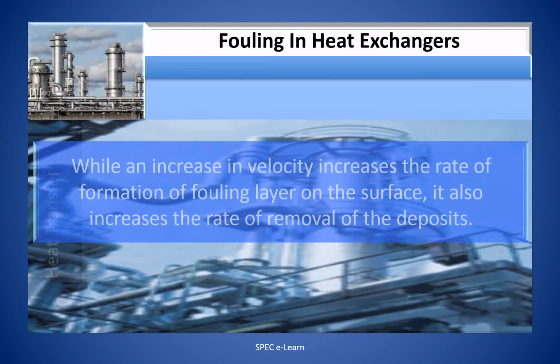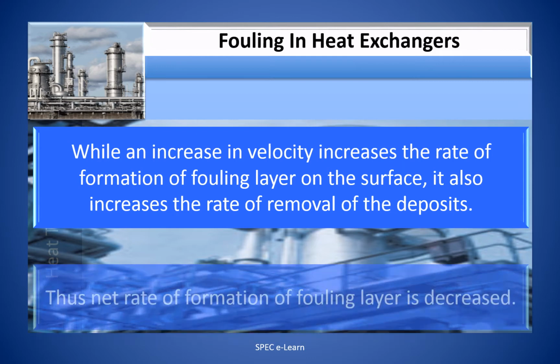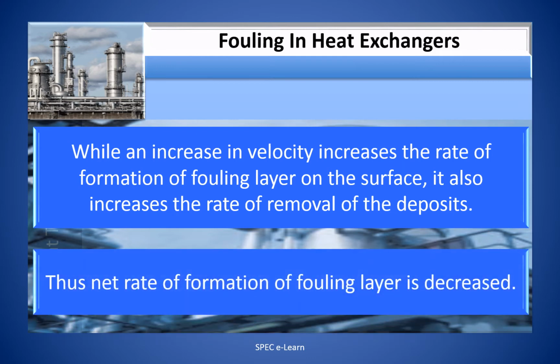While an increase in velocity increases the rate of formation of the fouling layer on the surface, it also increases the rate of removal of the deposits. Thus, the net rate of formation of the fouling layer is decreased.